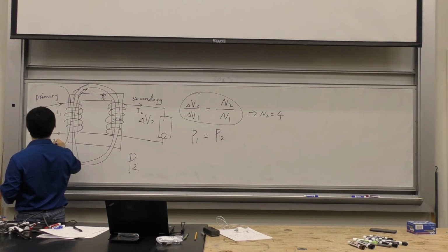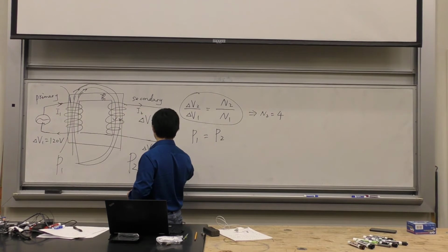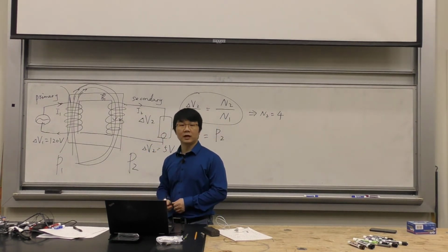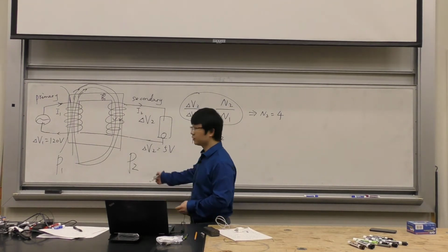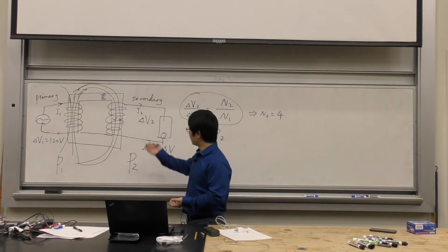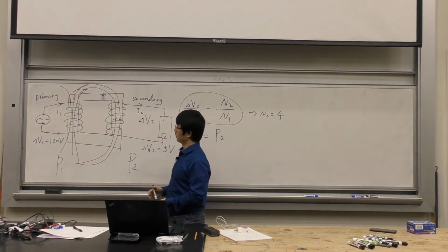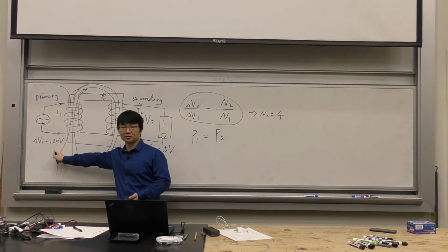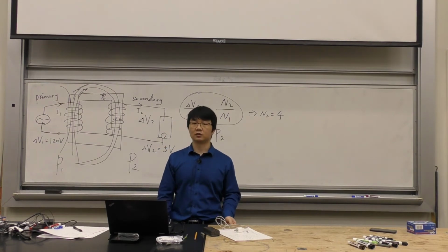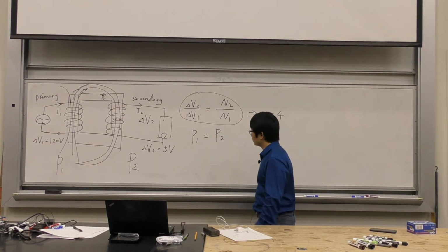So it's 120 volts. And then the voltage that goes to your iPhone is 5 volts. The rated output current of the charger is 1 amp. The 1 amp is on which side? It's on this side, right? The output current. This is the charger, and the output goes to your iPhone. So that's the input, so you're actually finding the current on this side. So how do you find that? Well, just equal the two powers. You can find the current. You can pause the video and do that.